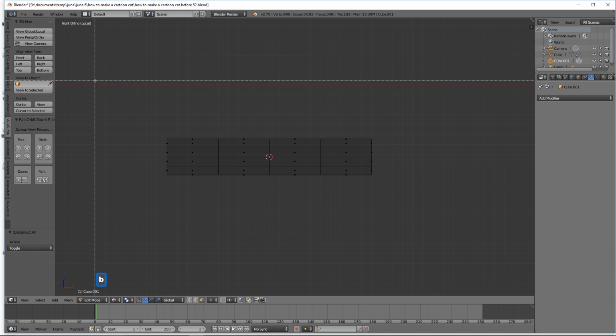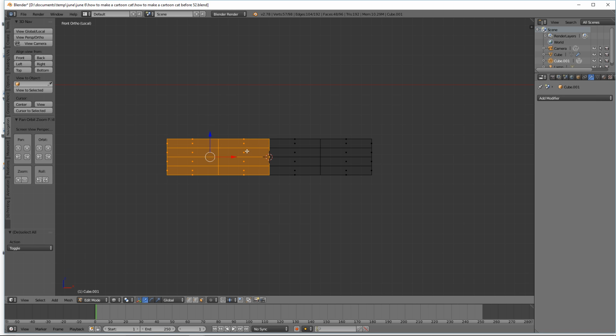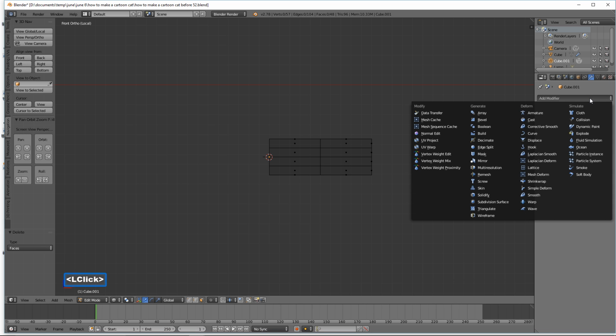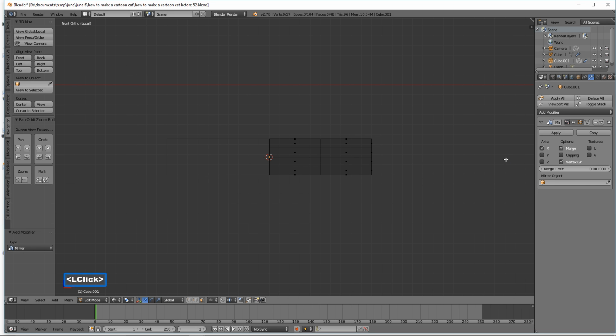I'm going to hover here, press B, and then go past that center point a little bit to grab all this. I'm then going to press X to bring up our delete menu, then choose faces to delete. I'm then going to click here and then go to the mirror modifier and click here. I'm then going to put a check mark next to clipping and then click here.